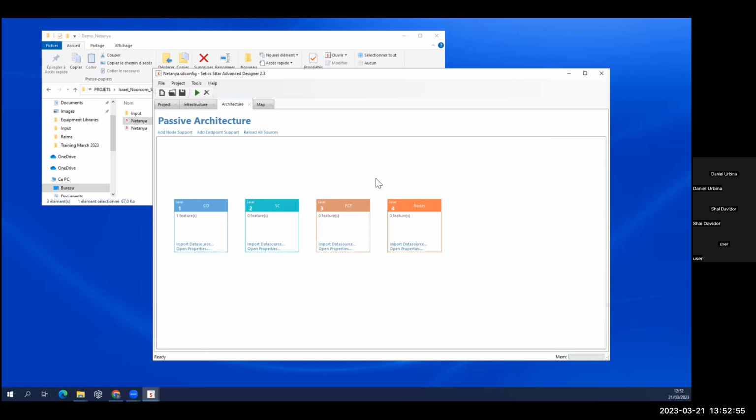Maybe the thing is that I'm trying to recreate a specific example in Netanya that was for a dense area, and we defined another intermediate level called SC because we wanted to force a specific type of cable from the feeder to this level. In the original, if we run from the central office to the potential level 2, the feeder cables were a bit different, not as we wanted.